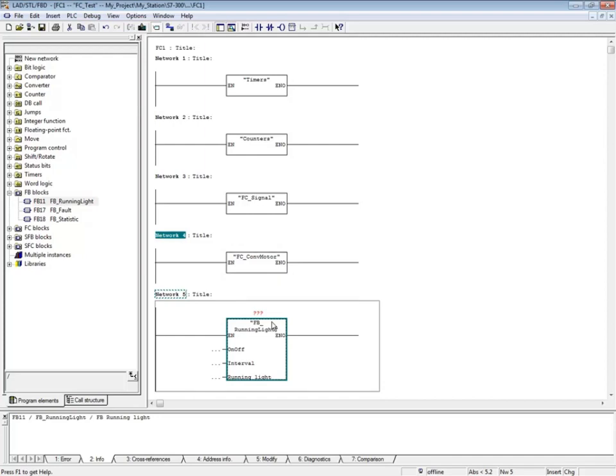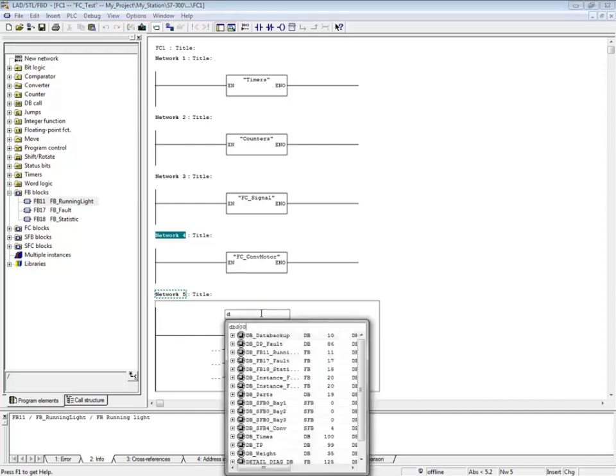When a function block is called, the data block must be attached for purposes of holding the function block's data. An easy way to create the data block is click on the 3 red question marks. Type DB followed by a number. The editor will not let you reuse a data block number, so you will not accidentally duplicate or overwrite an existing one. You can see what numbers already exist by looking in the S7 blocks folder.